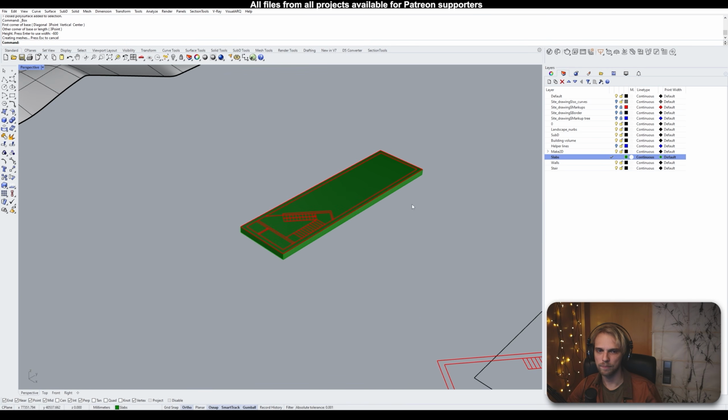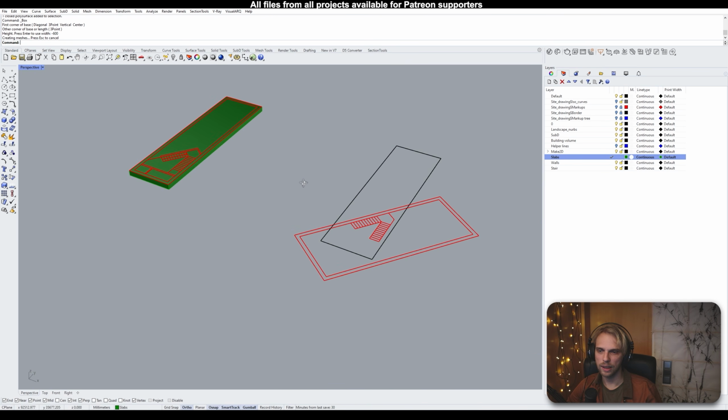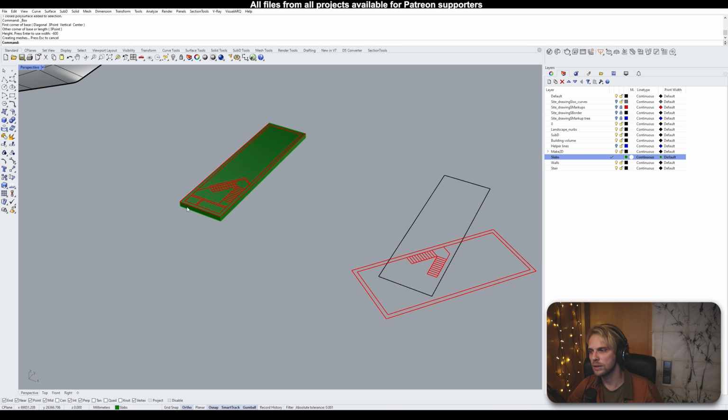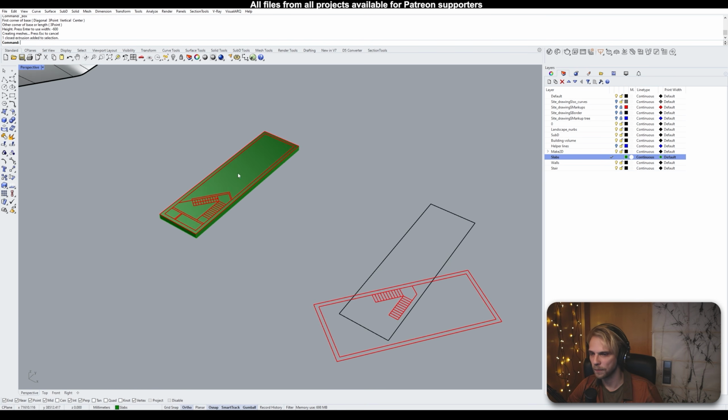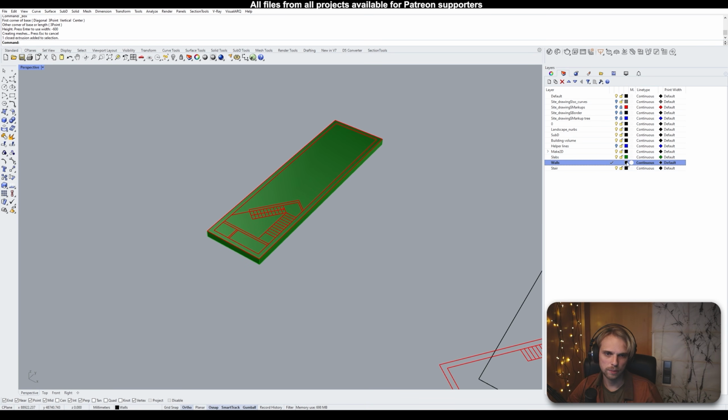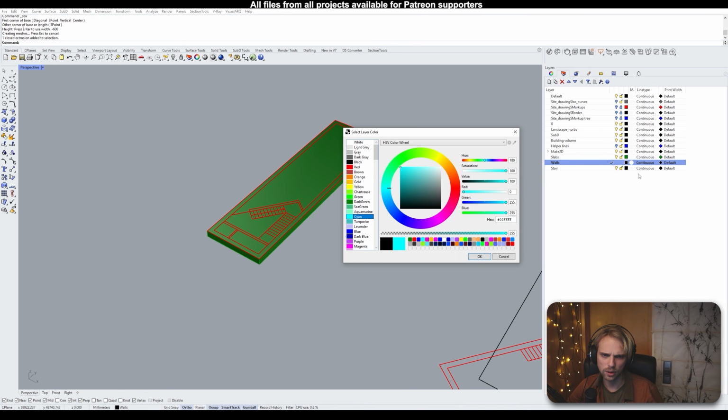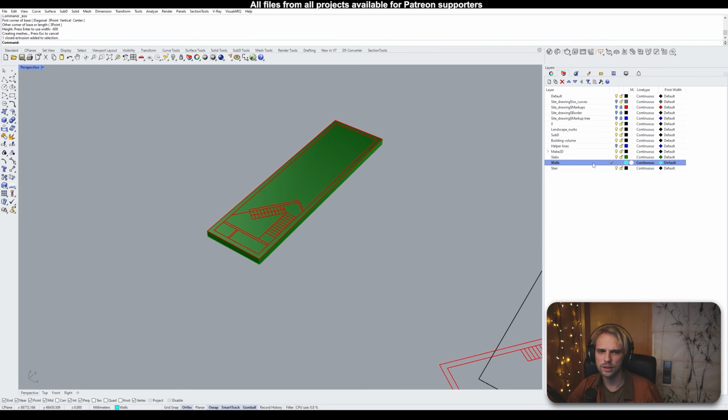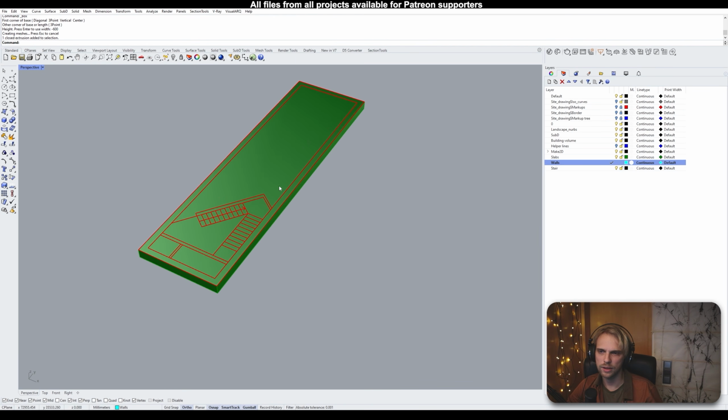That's our floor slab. Then we will have another one that's going to be our floor slab here on the second floor, but I believe we will do that a little bit later. So we're going to grow the whole building from the base layer upwards. Right, so I'll jump to wall creation and start creating walls. Let's choose some other color for the walls. Let's go for cyan and just start drawing.